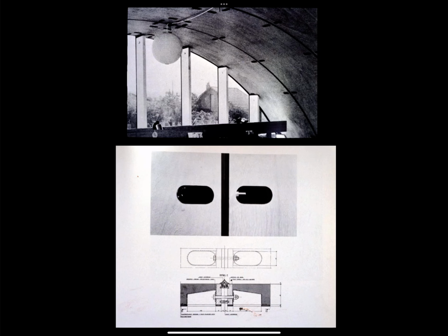The jointing system is a recess that is built into all of the panels in which you can insert bolts and bolt the panels together. And then the joints are sealed for weather protection with a neoprene gasket inside and out. So that's what gives the black line both inside and out.